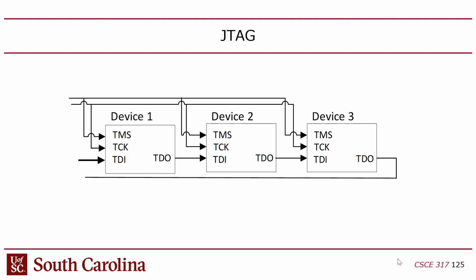So also the more bits, so the way this relates to you guys is that the FPGA is configured by shifting these bits in, right? Now the FPGA, think about this, it has 115,000 logic gates, right? Each logic gate is a 7-input lookup table to make a single 7-input logic gate.